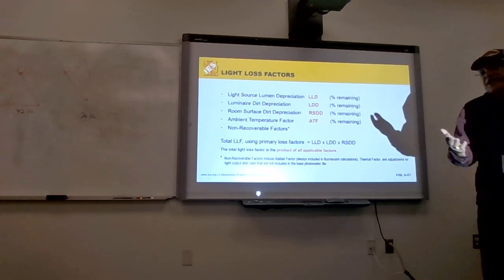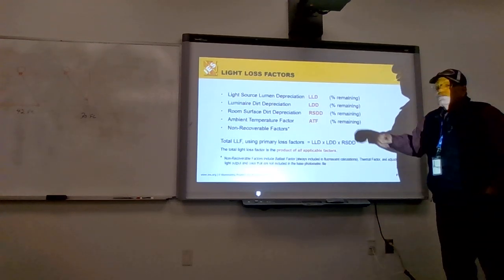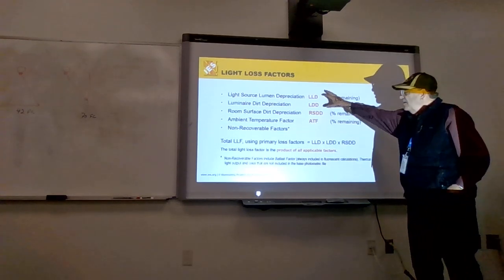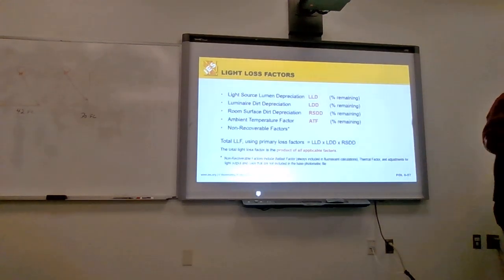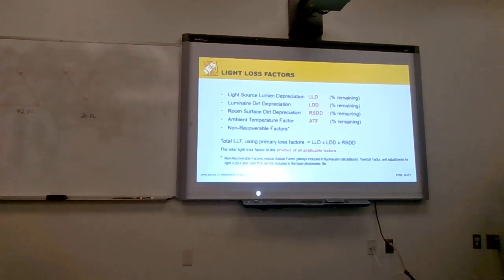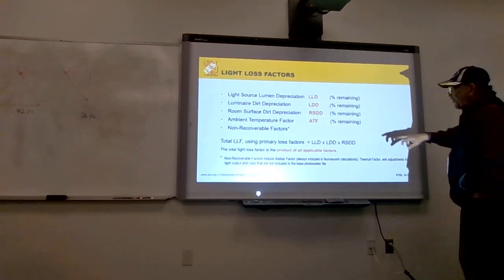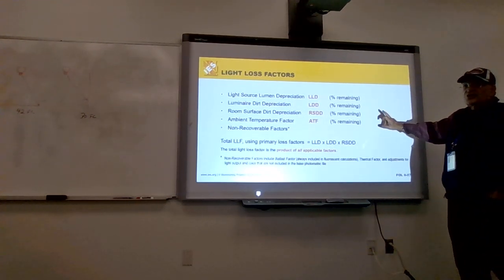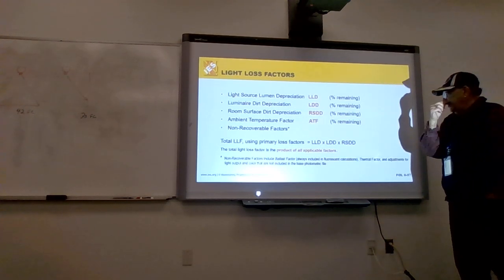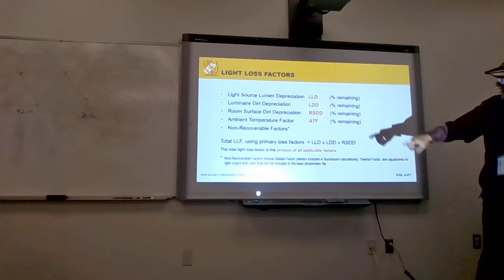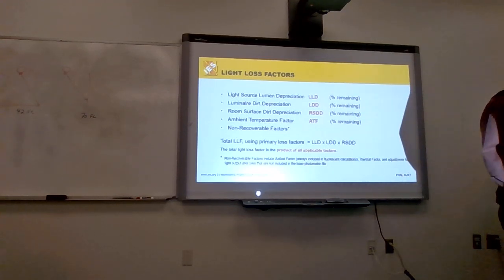Why don't we all agree on what the dirt depreciation factor might be, or the total depreciation factor might be, so we're all using the same calculation and nobody's cheating. And we determined that the actual factor that we were all going to use is 0.9 or 90%, 10% degradation over time, right? But in today's exercise, I'm going to give you all of these values.